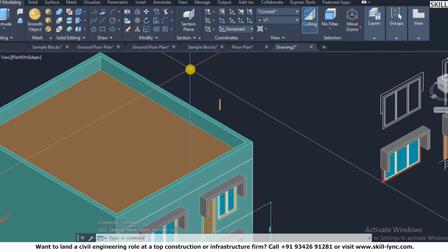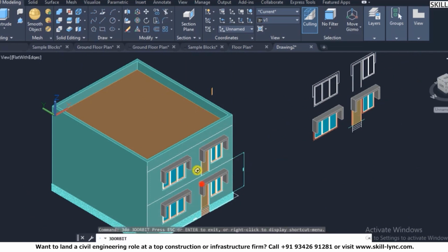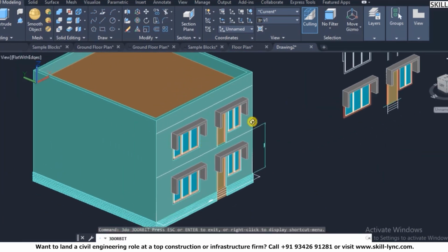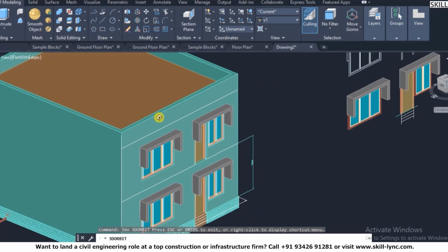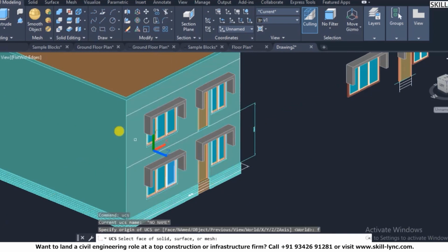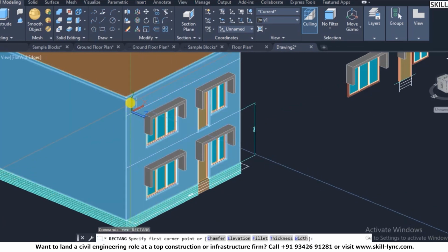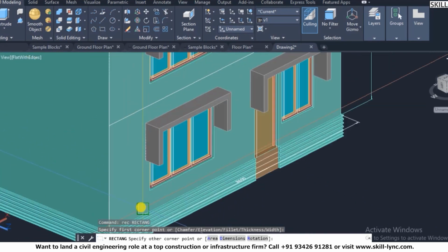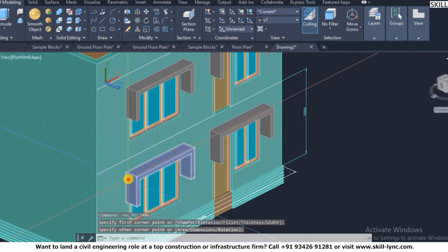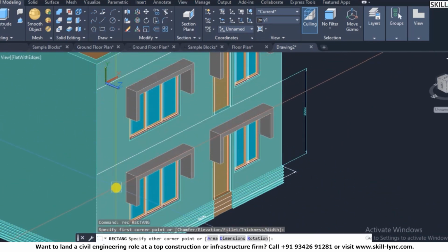with the terrace. So this is the building that can be created in AutoCAD by simple rules. So you can have some elevation and facade detail. Let's say if I want to put a UCS over here, and I want to have some detail, like I want to have a projection done at this particular point, so get a rectangle, REC. So see what type of facade design you can make.